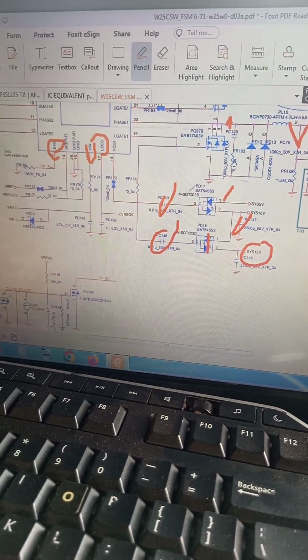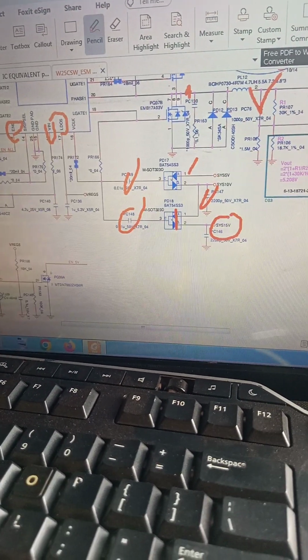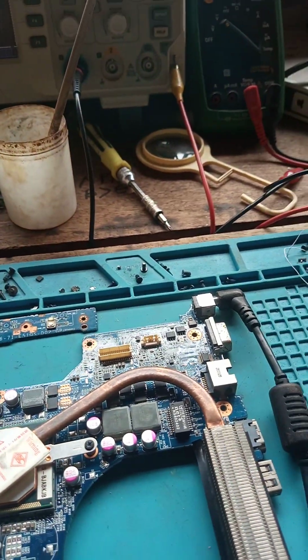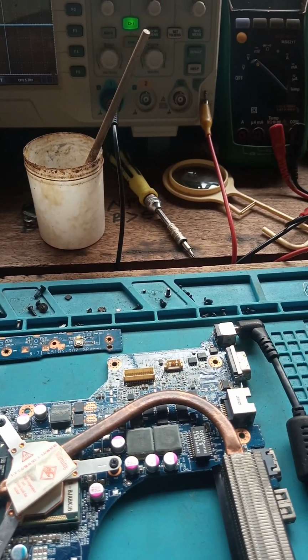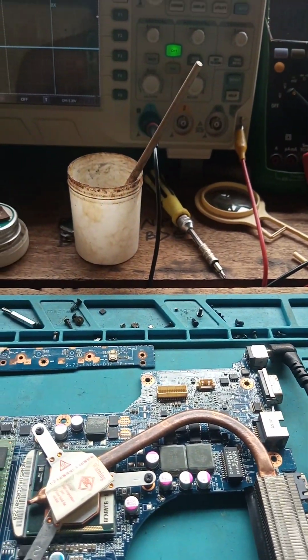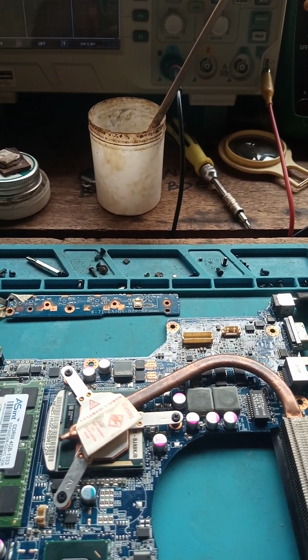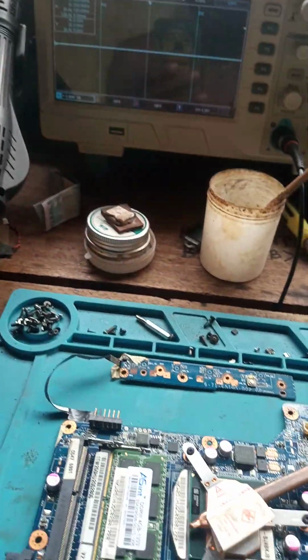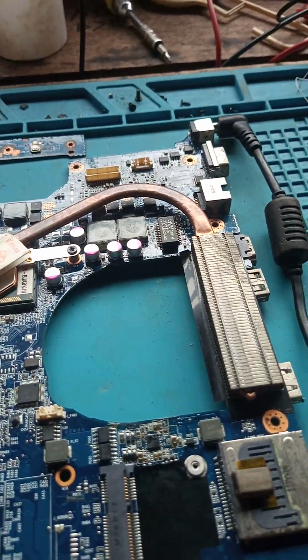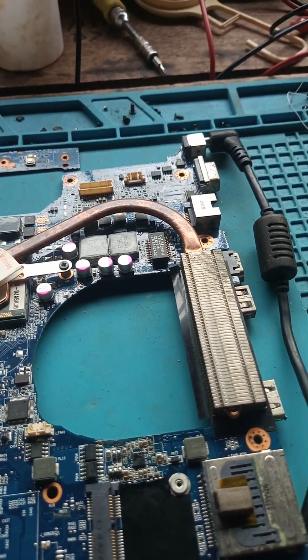This capacitor from 5 volts to 10 volts, from 10 volts to 15 volts. Then you have this run power voltage that will be generating your suspend voltages, 3.3 volt suspend, 5 volt suspend, your RAM voltage 1.35, depending on the RAM type, DDR2, DDR3, or PC3L or DDR3L, both are the same, okay?